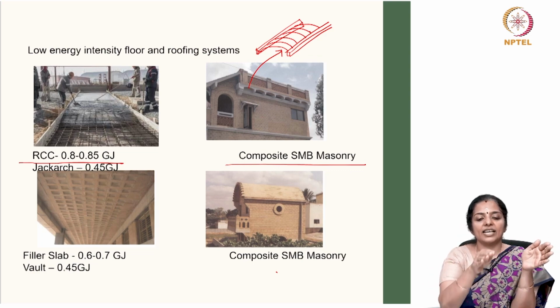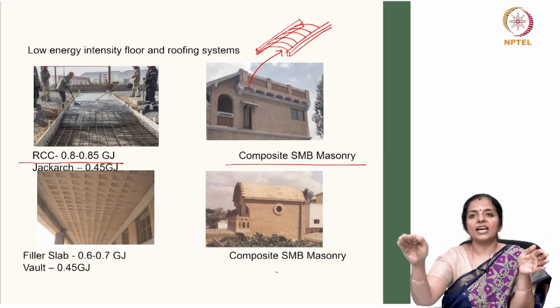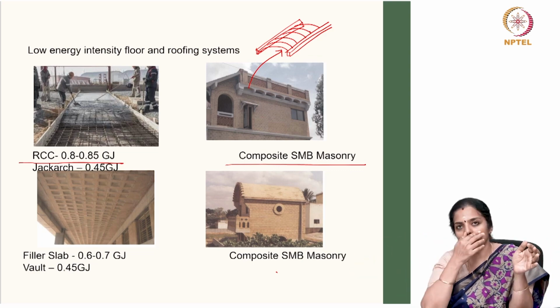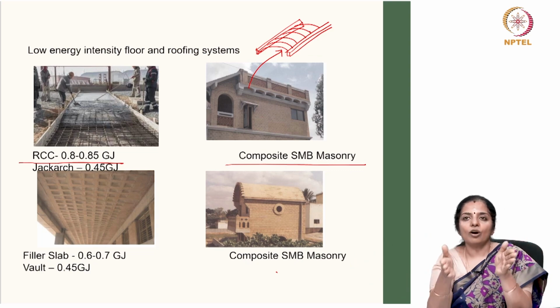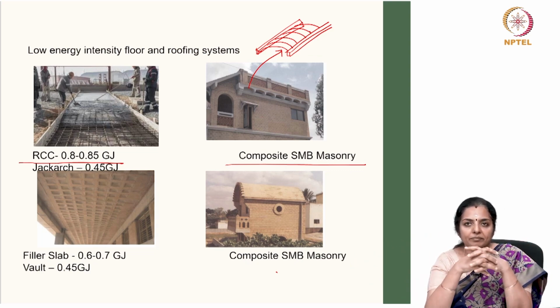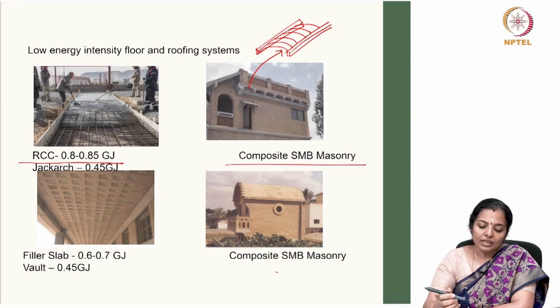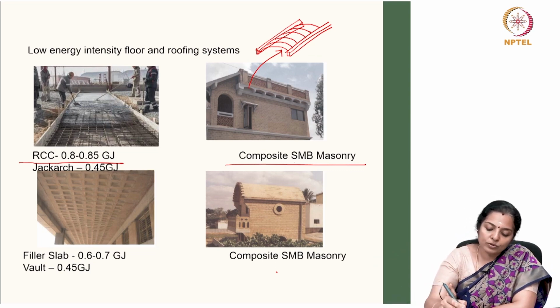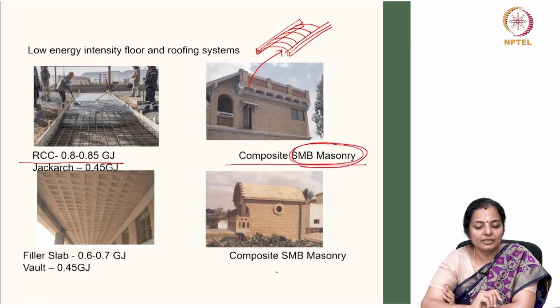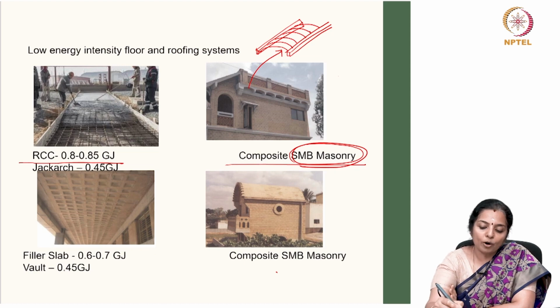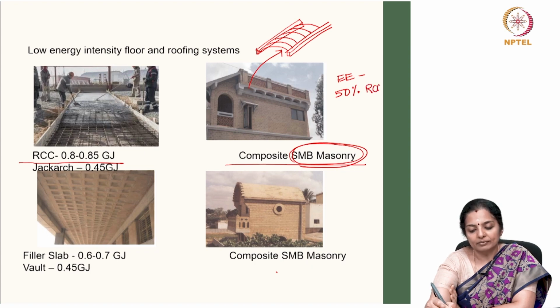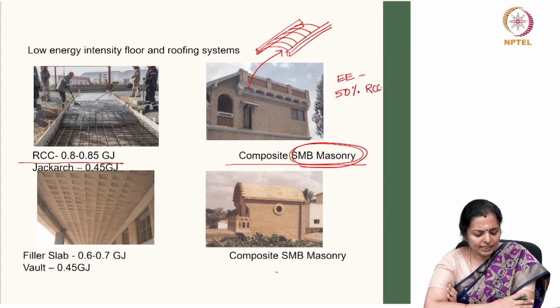So, they are a series of mild vaults placed next to another and on RCC beams. And if you see, by virtue of using stabilized mud blocks as the fillers, their embodied energy is almost only 50% of RCC.